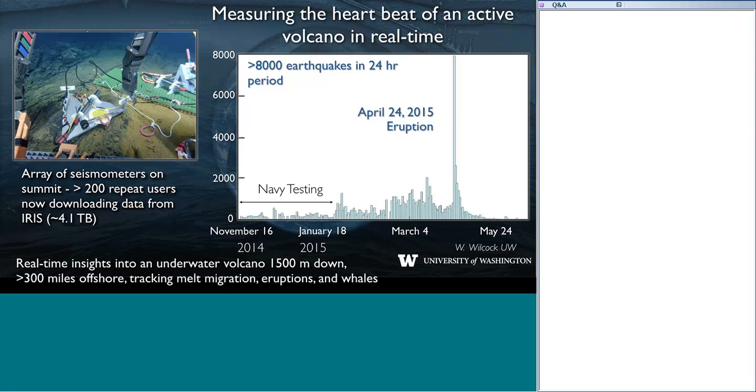And the seismic gear is sort of interesting because they have to be, this is a short period seismometer shown in the slide there to the left, and they have to be very level. So if you remember those games you used to play as kids where you put the little ball in the holes, that yellow platform there on the triangular shaped platform, there's a little ball in there that when they're totally flat, it's in the center of the leveling field there.